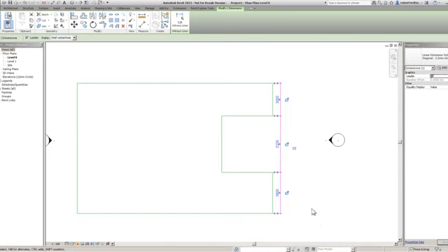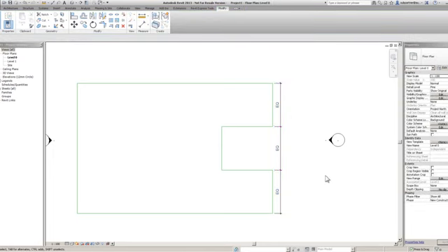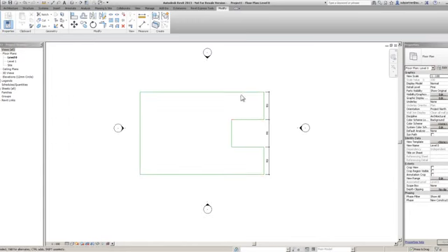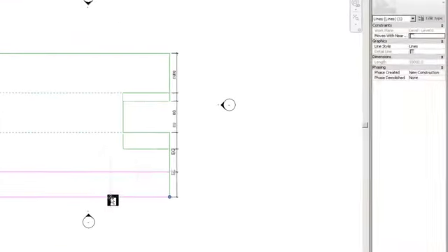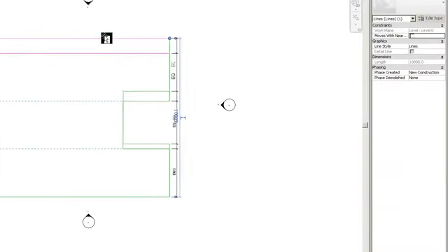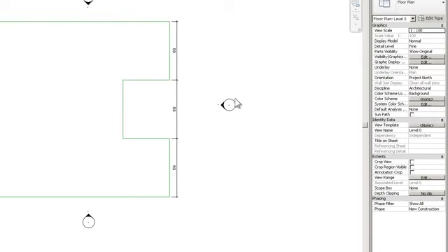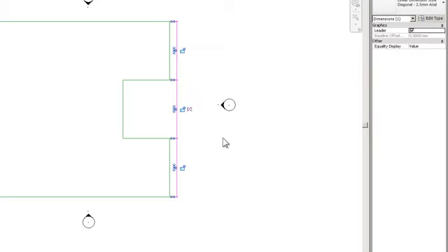Now, while it's selected, let's get onto these little objects just here. First things first, this one here called EQ basically puts an equals constraint on. Watch. Beautiful. All it's done is equalise those distances, moving the objects being dimensioned to suit those equalled dimensions. Now if I pick this and drag this out like this, can you see how they always want to stay equal? Very nice. To remove that equals constraint, I simply select the dimension again and cross through the equals.